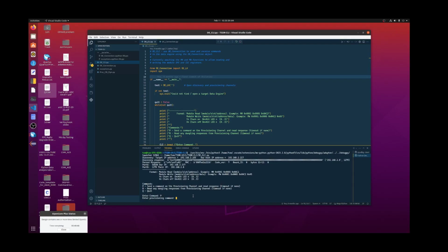The protocol lets us read and write registers on the target, and it identifies them by a module number, and on that module, an interface number. We have two modules in the system. Module 0 is the clock module, and module 1 is the receiver module. And each module has multiple interfaces.